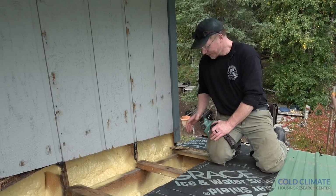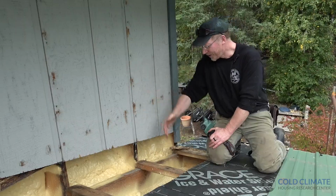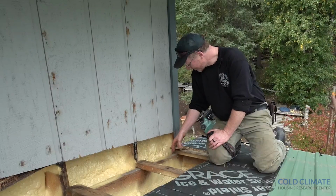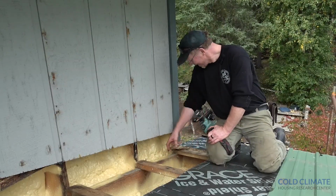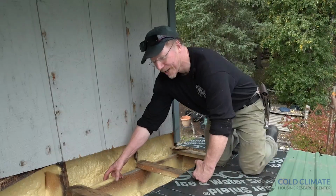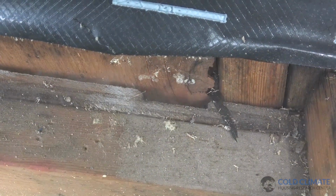Our second problem starts here at the bottom of the roof, but it extends all the way up to the peak, and that is when the addition wall, the new wall, was butted up against the house wall, suddenly the old house T111 siding became a conduit for indoor air to leak up into this rafter bay here and into this wall. All the way along here, I can see the old siding hasn't been sealed. There's some foam overspray here, but that's incidental. Not only is the sheathing joint where it meets the rafter an air leakage spot, but all the vertical channels in the T111 are also pathways for air leakage.